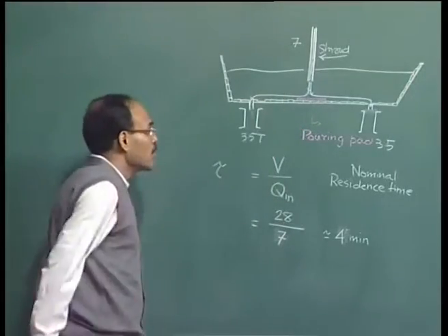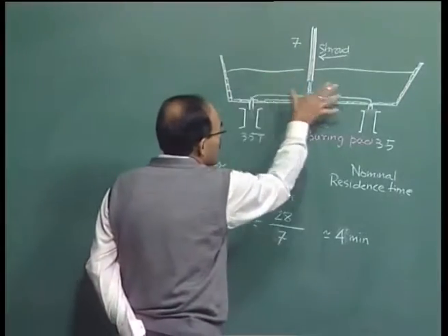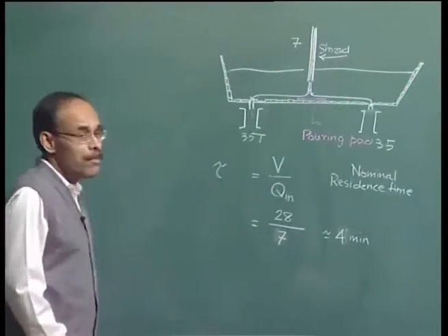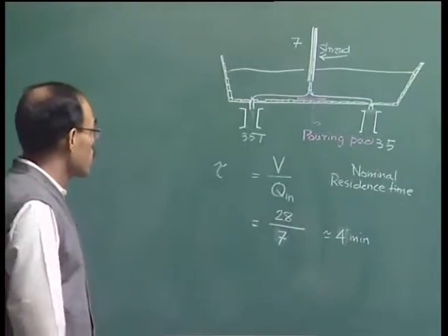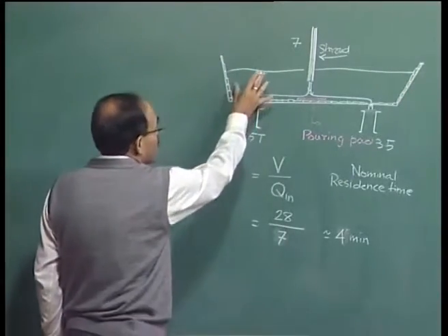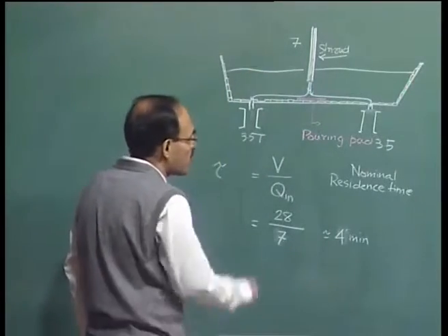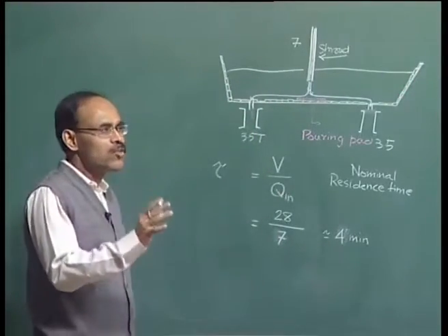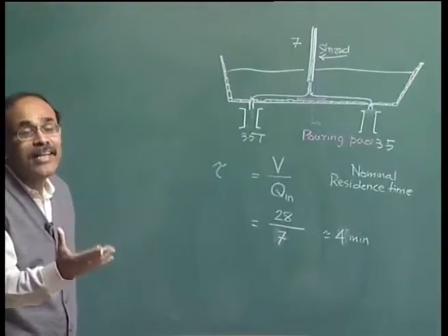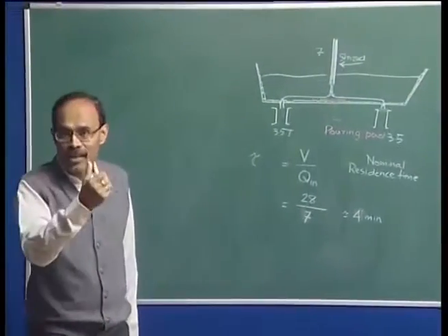And tundish processing, as I have mentioned, the tundish need not be looked at today as solely a distributor of molten metal, particularly when we are talking of quality improvement. We are talking about inclusions removal by enhancement of steel quality, as well as minor adjustment of composition and control of temperature also in the tundish itself. So, the tundish should not be looked at as an idle reactor. It is a very vital processing reactor where the quality of steel can be significantly influenced.